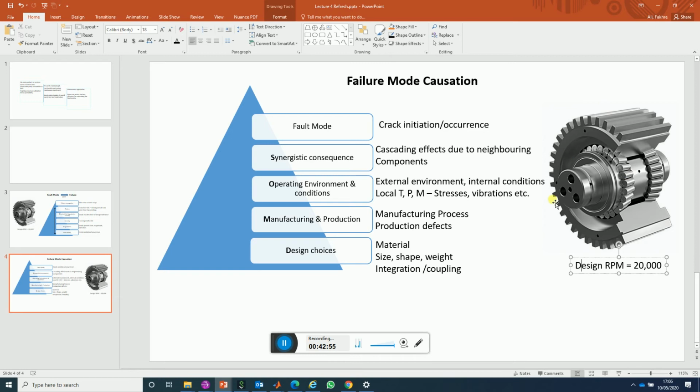So, we're supposed to supply 5 liters of a specific type of lubricant yearly to this particular gearbox, but because we don't do that, it leads to metal to metal friction, and that raises the temperature within this gearbox, which leads to basically stresses and vibrations.